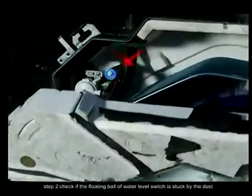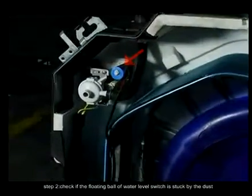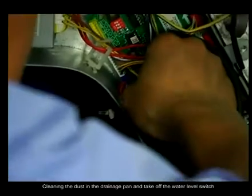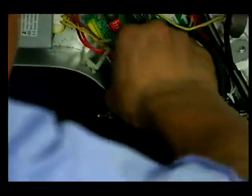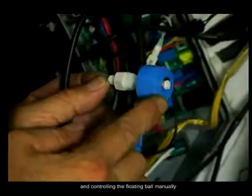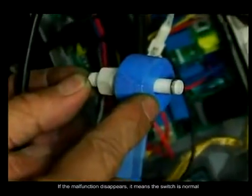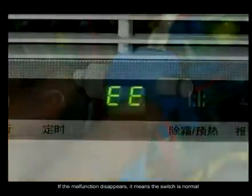Step 2. Check if the floating ball of water level switch is stuck by the dust. Clean the dust in the drainage pan and take off the water level switch. Connect it to the main board of other indoor unit and control the floating ball manually. If the malfunction exists, it means the switch is broken. If the malfunction disappears, it means the switch is normal.